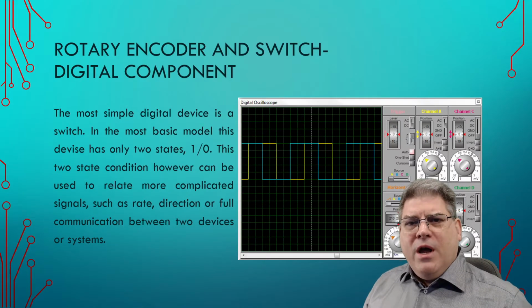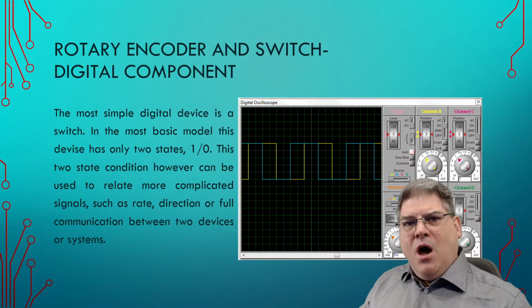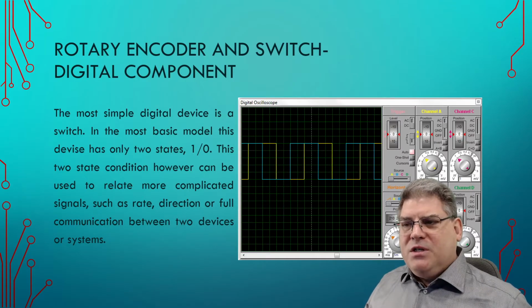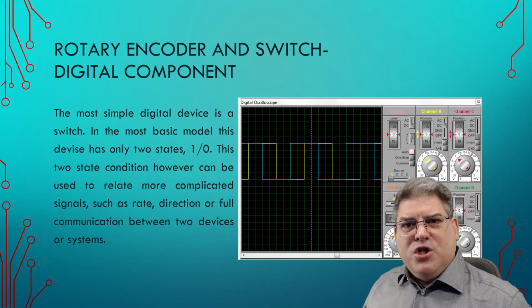So a rotary encoder is basically a switch or a pair of switches that, as you turn it, an optical beam gets broken, typically by an engraved piece of glass or plastic, and so this creates ones and zeros as you turn it. And as you can see from the little example here, it's able to pulse, okay? And the faster those pulses come, the faster the computer knows that you're turning it, okay?